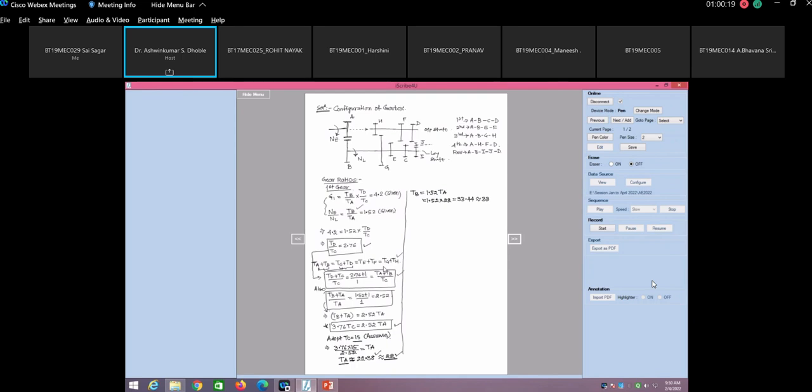So sir, we have taken this TC as 15, and accordingly TA comes to 22 and TB comes to 33. Now just see this 22 plus 33 becomes 55. So this is 15. So this gear is going to engage with gear D. So gear D must have 40 teeth to make the sum of the teeth equal. We are assuming the same module for all gears, right? Yes, sir. What is module basically?